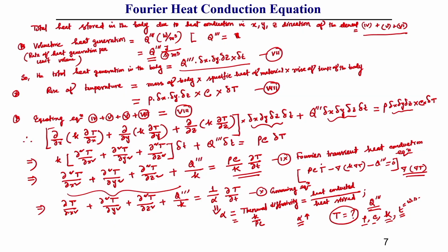If you use temperature dependent material properties, that will give you a more accurate result during your calculation. If you use constant material properties, that also gives you some temperature history over the entire welded joint as well as the plate, but it can be a little bit erroneous.